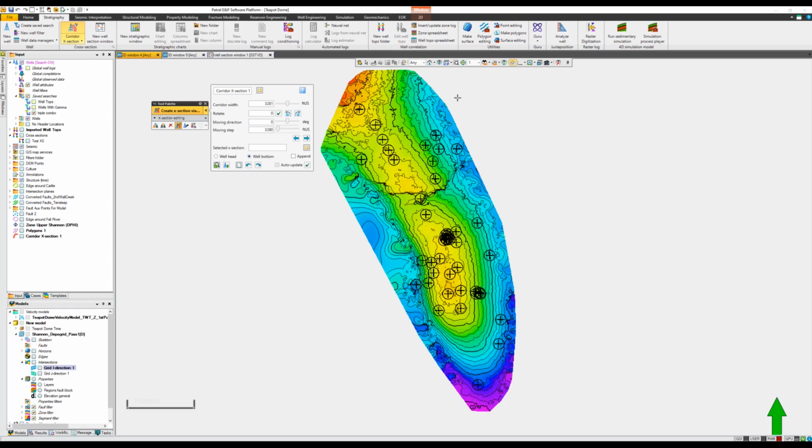First, digitize a polyline by using your left mouse button. While you can place any number of points in the line, keep in mind that the simpler, the better. Once you have created the line, you can adjust the corridor width with the slider bar.